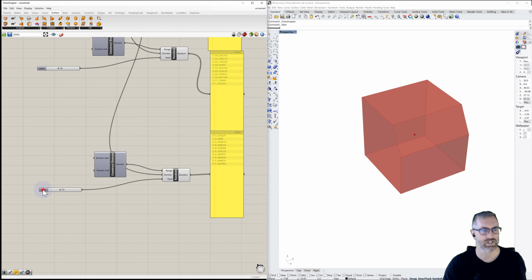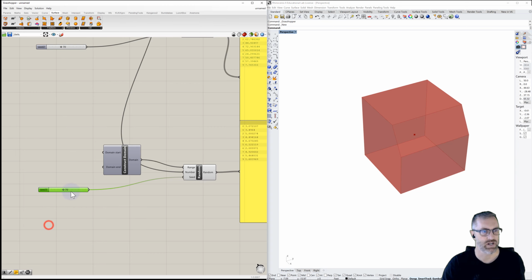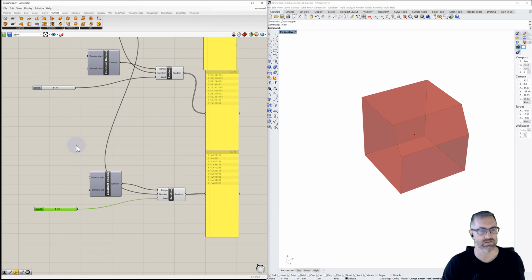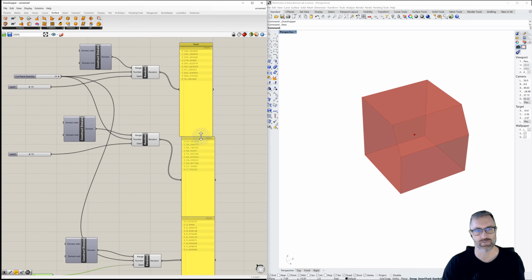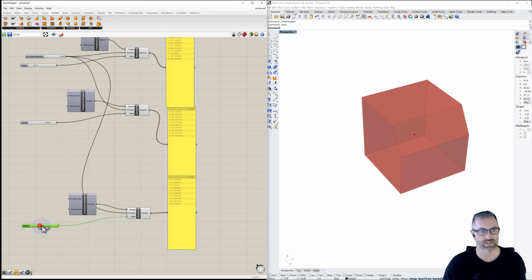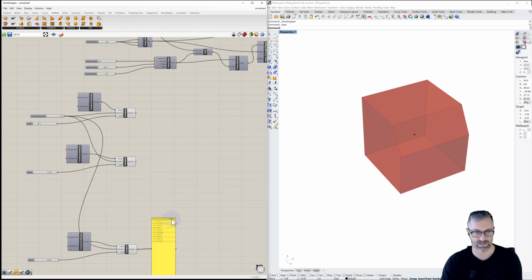The seed value, we'll change this to seed 3. You'll see there that I'm leaving them all set to 70 now to see what results. And so there's a different set of random numbers within there. But you'll see as we change the seed value, these will change and randomize, and so will these. If the domain was the same, and the seed was the same, and the number of the list was the same, they would be the same numbers. And so this gives us a couple of options here. I can delete the panels just to save some space now. Hopefully you get a sense for that.